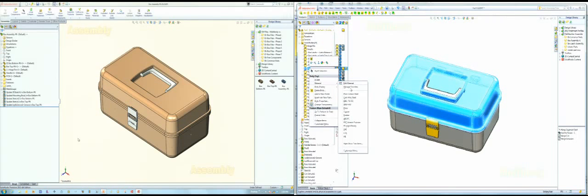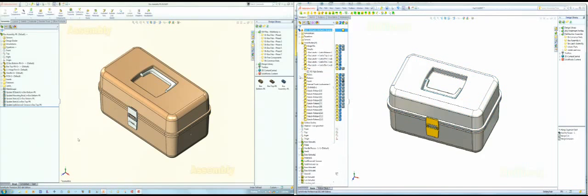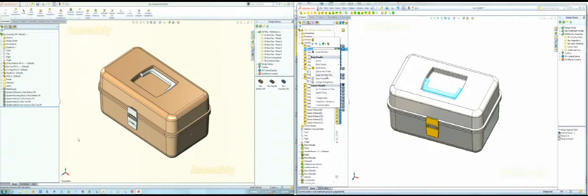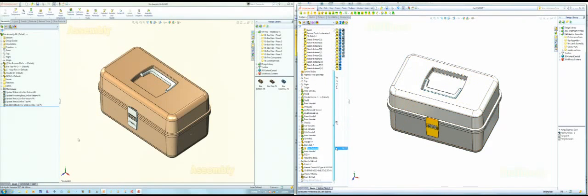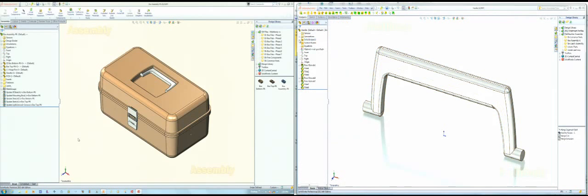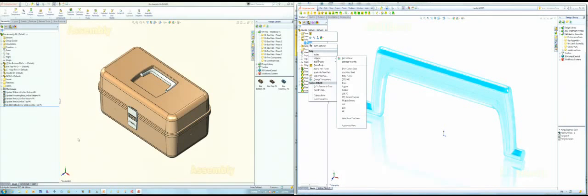So it's changing the materials right on the tree of the solid bodies, okay? We can also do it to the parts we brought in, but if you can't do it from here, for example, the handle, if we right-click on here, there's no material. So the way we have to handle the handle is we have to go out to find the handle, edit it in context, and then go up to its solid body folder, and there's a material because this feature was created internally in this file. And then we can change it to polyethylene.